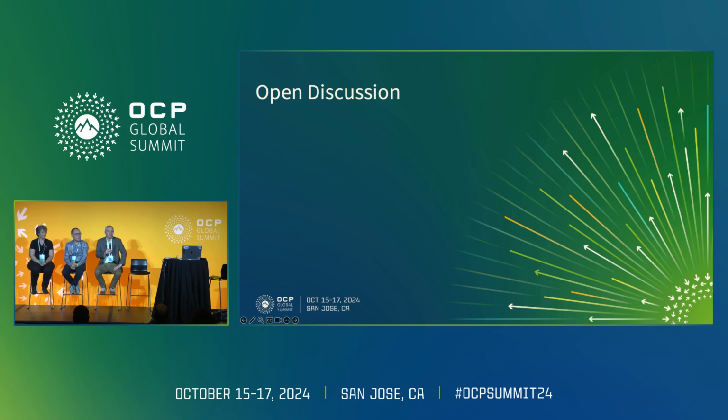Yes, so good point. It might not be free. Some of those sensors are free, like path margin monitors are free. There's other ECCs per unit time is free. Drew mentioned, though, that he had to debug for 9 months to find his issue. And I've been listening to a lot of these data center folks. They're running regular software loads at the operating system level and trying to find random defects by throwing random data and random instructions at their system, hoping to find something, right? Wouldn't it be good just to take it offline for 3 seconds, and just periodically test something at, let's say, low voltage, high frequency, whatever it is, to kind of sensitize a marginal part.